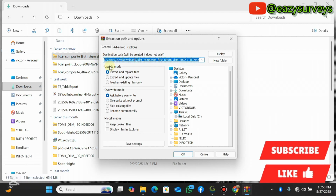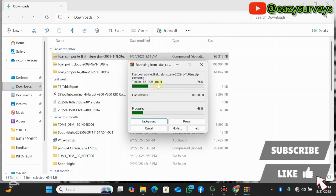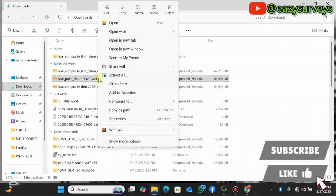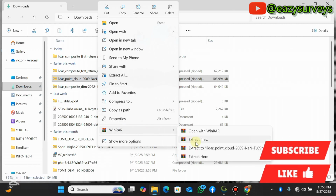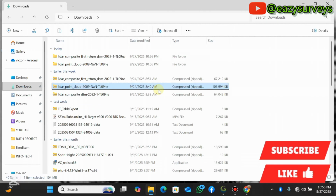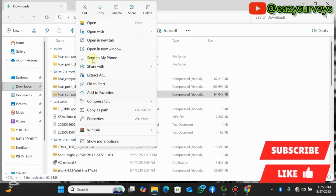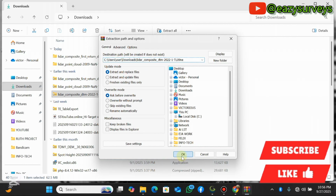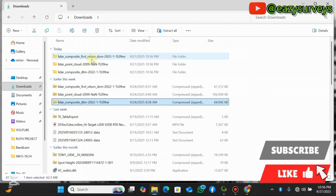I just want to extract the DSM. That is done extracting, and I'll go ahead and extract the LiDAR point cloud for that same study area, and that is already done. And lastly, the DTM. Extract, and that's done also. All right, so I have the 3 sets of data.